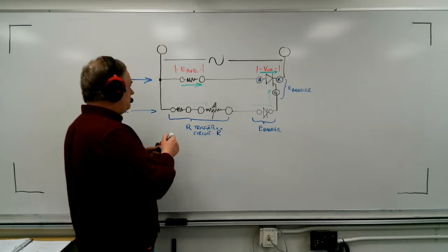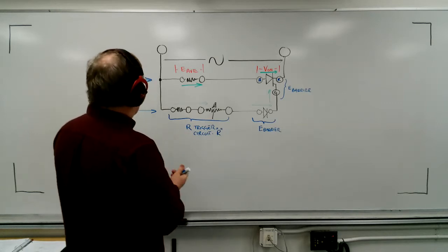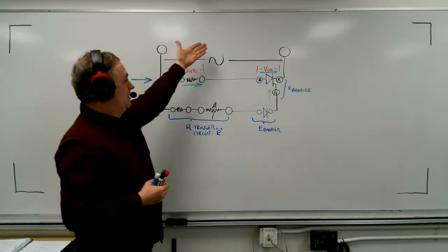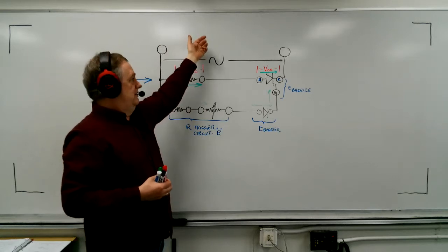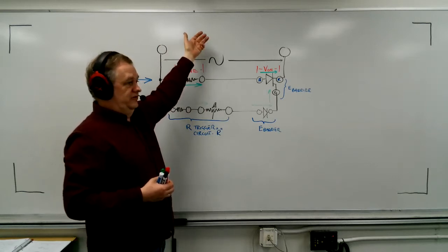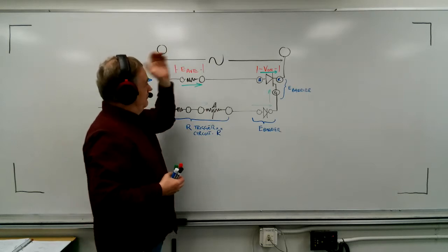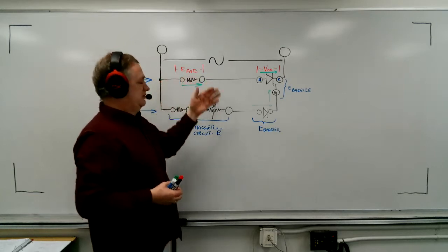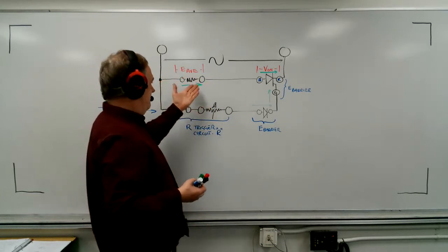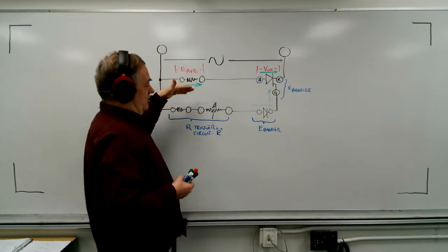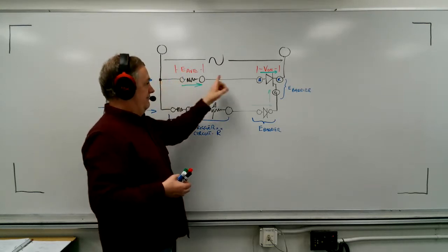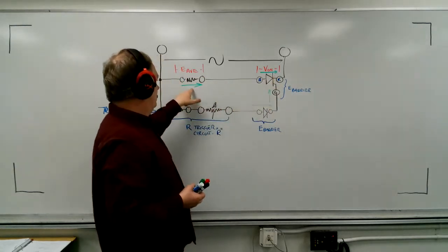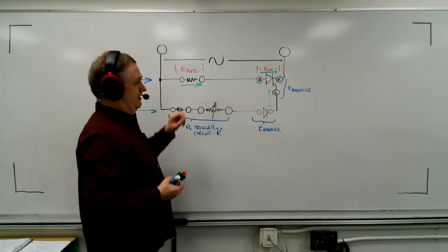And so then if we look at this other circuit, here we have, and this is quite common, line voltages of 120 volts are very common for that. And so here we've got our AC line voltage, and we're going to have a load voltage that's probably at least 45 volts at its highest level, and then of course down to about 22.5 volts if we adjust this so that it fires at 90 degrees.